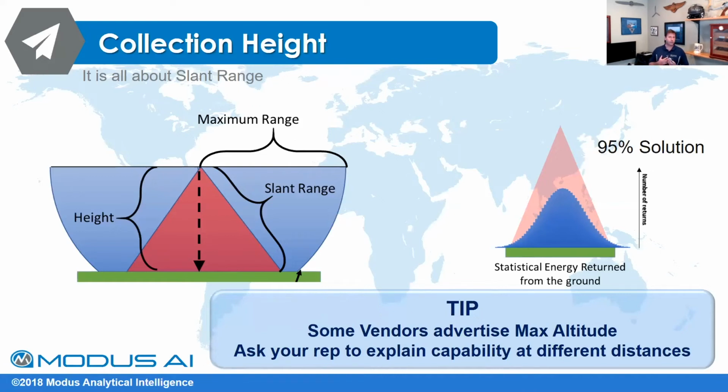My personal preference is I set filters so that I don't see anything in the blue example here, so that I don't get any noise in my solution. Some people turn it on and just filter down the backside. But the most important thing is to understand where your field of view is and how much area you're covering, because this translates to efficiency. And the most expensive thing in the field is your field time, with people, labor, travel, and all that. So you want to minimize how much time you're in the field, or maximize how much area you're going to cover.